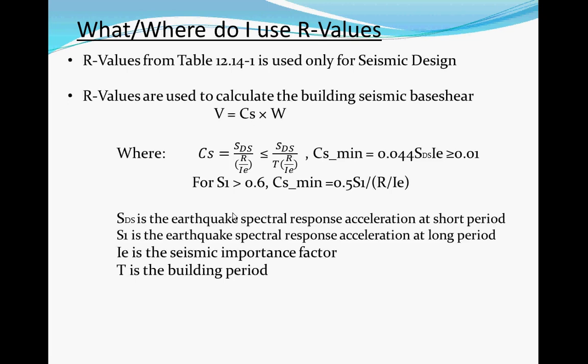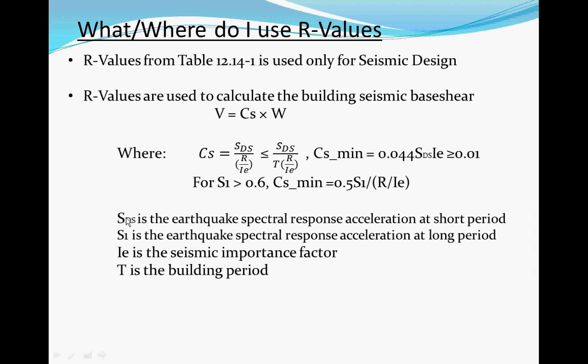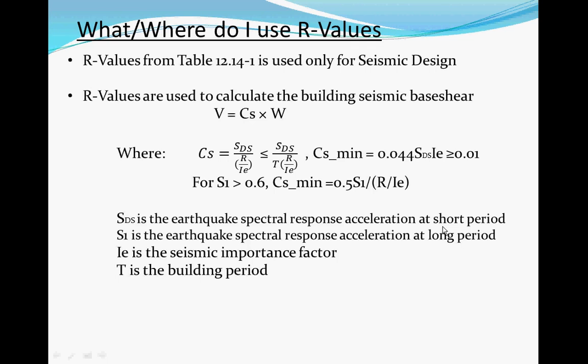Okay, so SDS is related to, I would say, a response acceleration, site dependent. So the more earthquake-frequent the zone, the higher the SDS value you'll see. Okay, it's related to location, geological location. West Coast, you see those high SDS values. East Coast, small SDS values. And these are all in SDS, SD1, S1. All these are published in maps. And we'll show you what those are.